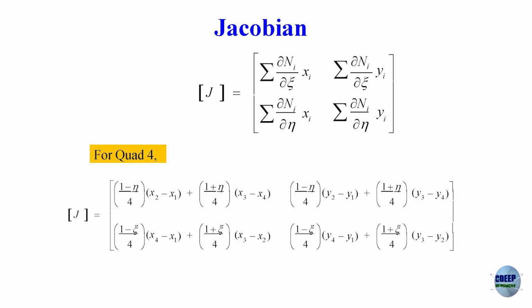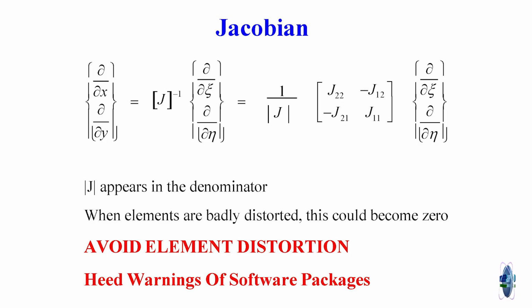Then it depends on the particular shape functions that you use and the actual real world physical coordinates x1, y1, x2, y2 etc. and enter into the Jacobian. Okay. We also discussed that the Jacobian determinant would be in the denominator, therefore, elements that are badly distorted leading to poor Jacobian related issues would be there affecting the performance of the element. That depends on the mesh. Now, element is frozen, that means the shape functions part of the Jacobian is frozen once you chose the element.